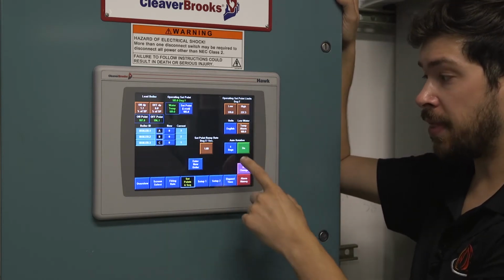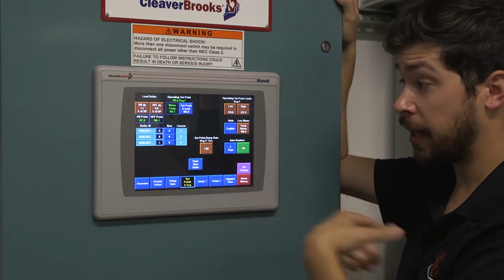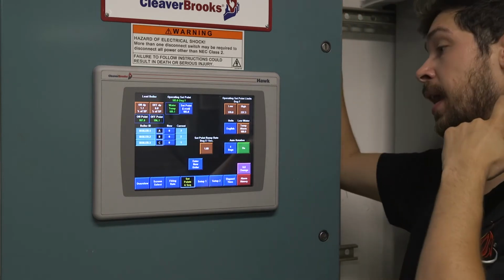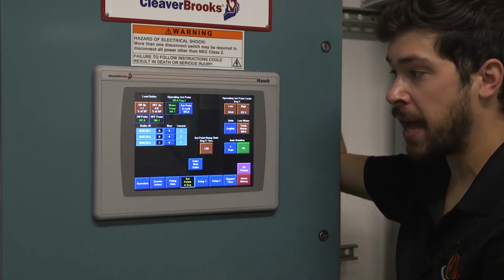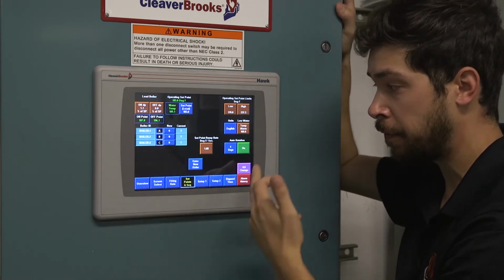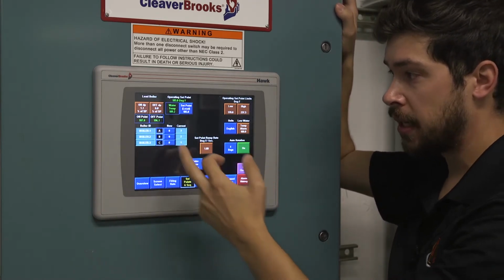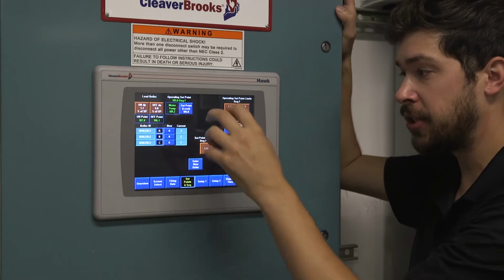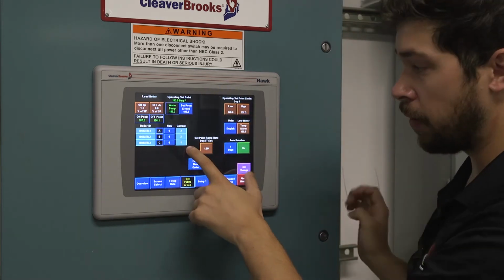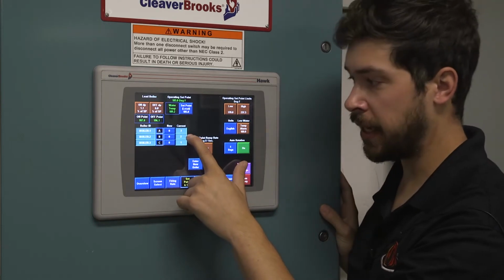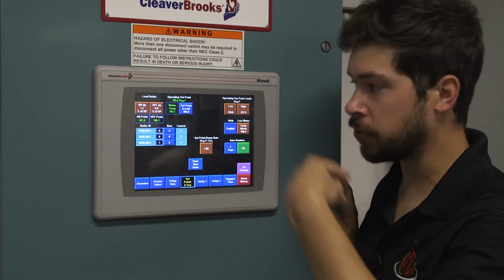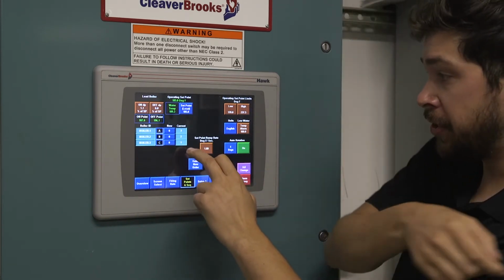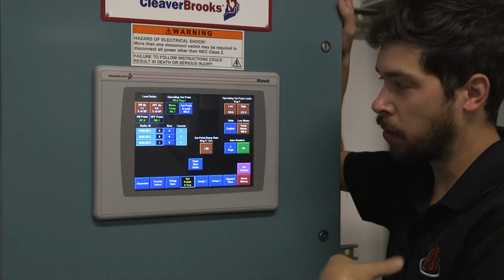Really just hit on, and then every 4 days on the count, just elapsed time, not necessarily run time, just 4 elapsed days, this will automatically switch over. So we go from running boiler number 1 for 4 days, then we'll run boiler number 2 for 4 days, and so on. We actually would follow this path. We wouldn't shuffle the numbers around. We would just go from boiler 3 to boiler 2 being the lead, to boiler 1 being the lead, and then keep running through this sequence. It will automatically shuffle around these numbers. It won't change the order of it.